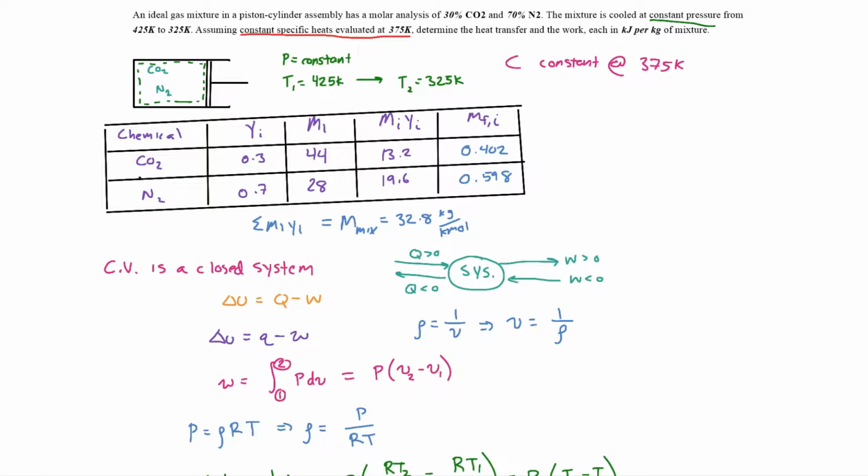There are varying assumptions that you can apply, because the change in enthalpy with respect to temperature can be fairly constant, and then you can approximate that. You can use thermodynamic tables. There might be iteration processes that involve plugging in numbers and seeing if that makes the equation true. If it doesn't, you replug in numbers and iterate through the table to calculate that temperature, if you're looking for temperature, so to speak. So what I'm saying is that there are a lot of ways to go about these problems because you're given different methods to solve the problem.